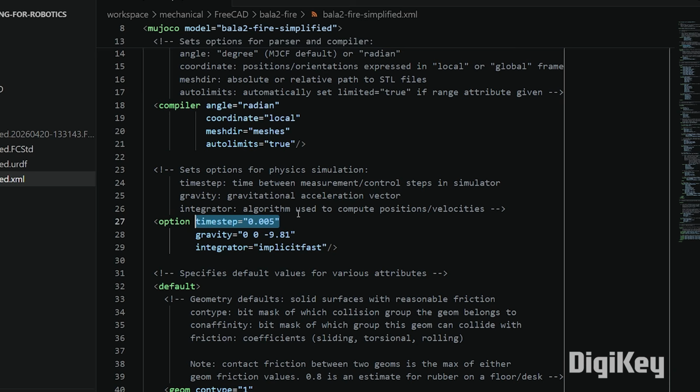If you're finding that you cannot accomplish that in firmware, for example, your microcontroller is too slow or inference takes too long because the neural networks are too big, then you will have to come back to this option right here and increase the time step and hope it doesn't ruin the robotics as you retrain everything. So this is an incredibly important parameter.